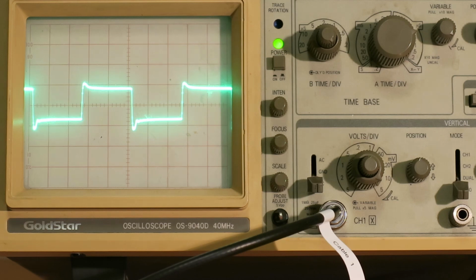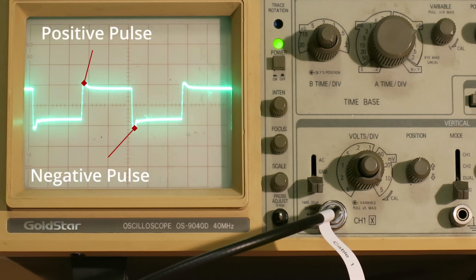This waveform is a combination of 2 waveforms, the result of 2 different coupling mechanisms. The first mechanism is magnetic field coupling. This results in a series of positive and negative pulses, which are induced as the square wave current waveform from the signal generator changes polarity. This type of coupling is frequency dependent. Therefore, the contribution that this type of coupling makes to the overall waveform seen on the oscilloscope screen will change with the frequency of the interference waveform.